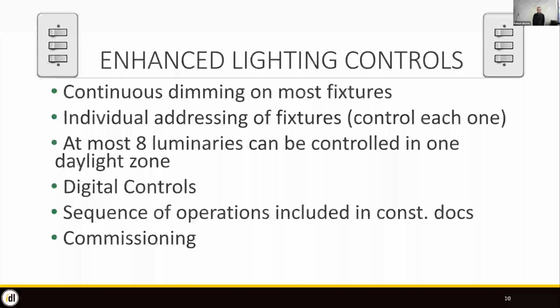That is a good question, because it depends on if you're looking at occupancy controls or if you're looking at daylight dimming, and then individual zoning of the spaces and optional dimming. There's different percentages associated with each one if you're doing an energy model, and LEED and 90.1 will lay out some of that.